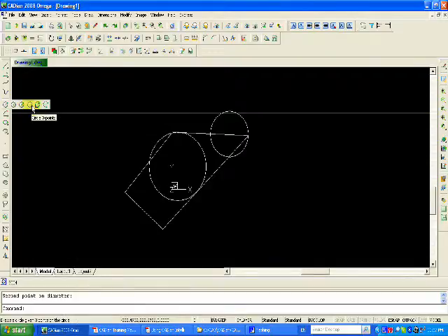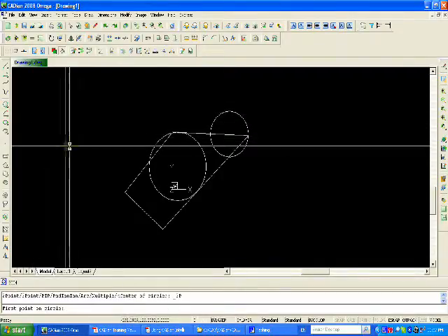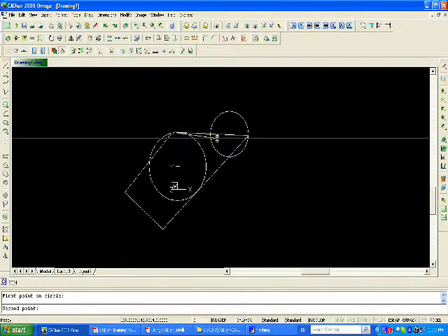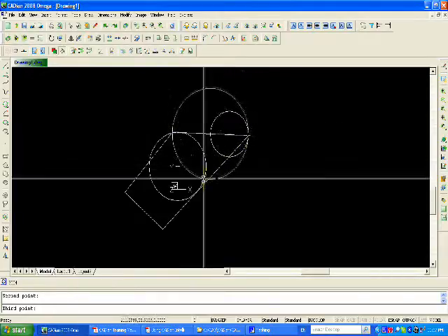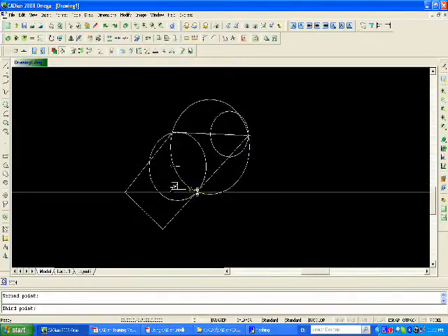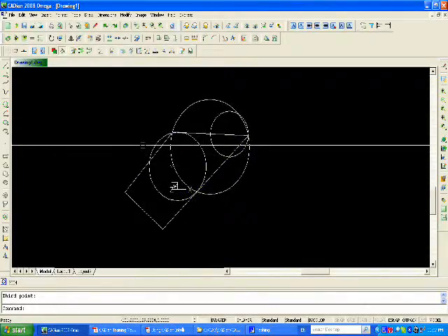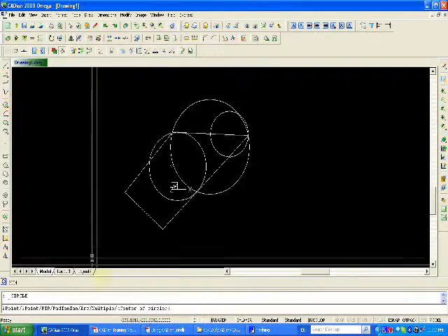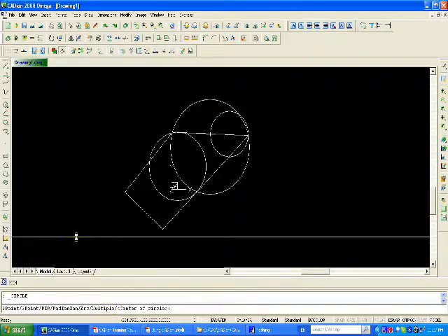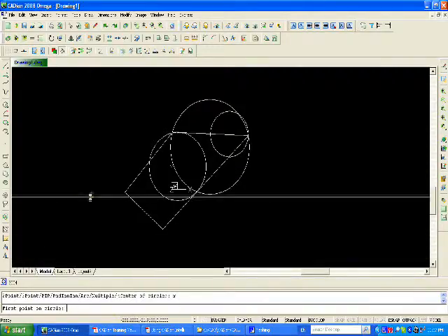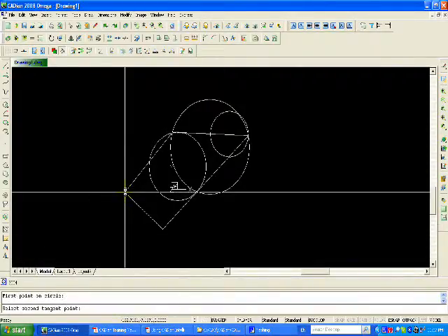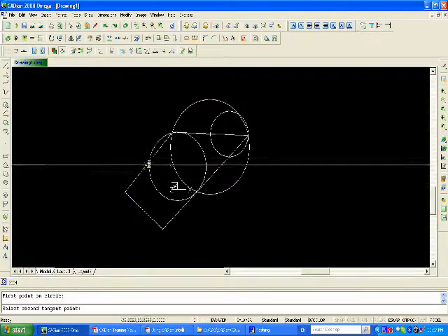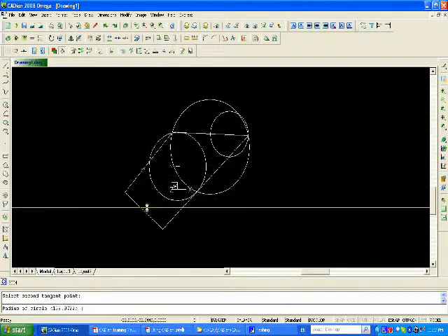Go back to our 3 point. What's the first point on the arc? Is circle. Second point is there, and the third point. If you know 3 points on a circle, this is the kind of tool you're going to use. But you can use one command and literally, let's pick multiple here, and it asks me the first point on the circle. It's going to be there, and the second tangent point, which is kind of crazy, and the radius of the circle is going to be 100.